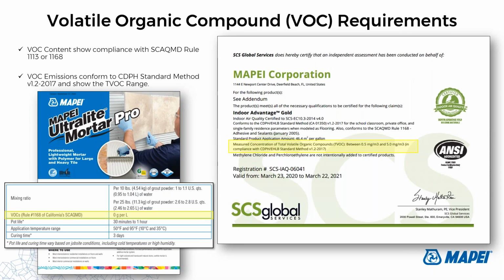Here's an example of VOC content on the left. VOC content is typically found on TDS or SDS. And on the right, there is a third-party VOC emission certification that you would gather as part of documentation for projects pursuing green building certification. MAPEI has over 400 products that have undergone testing and certification showing CDPH compliance. So we have a lot of these third-party certifications on the right.